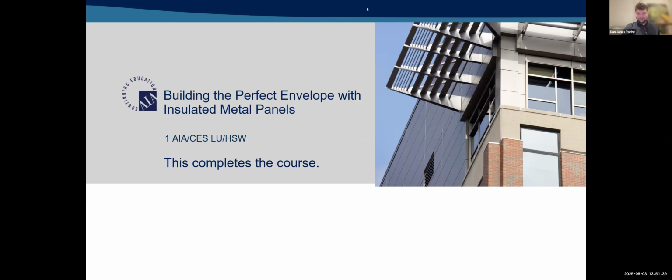How can the single component insulated metal panel be seen as more reliable than the multi-component rain screen wall system? Isn't one point of failure a concern? That's a question I hear quite a bit, of course. The first thing that I say is looking at that multi-component system, where there are multiple points of failure. And one of the problems there is if there's a failure, let's say in the vapor barrier, how do you know? Because it's concealed, it's inside all this other system. And my examples early in the presentation showing the moisture inundation in a wall, those sorts of things can happen.